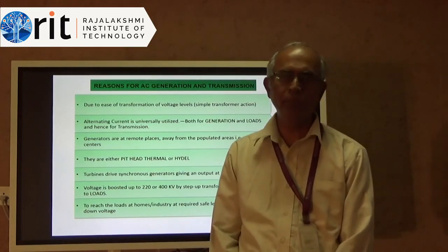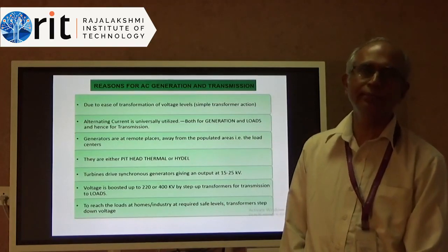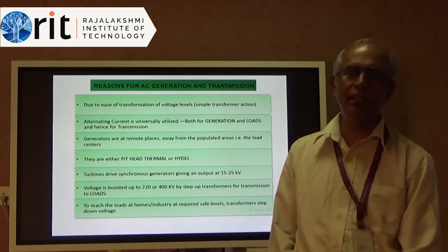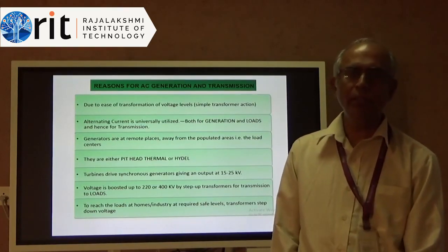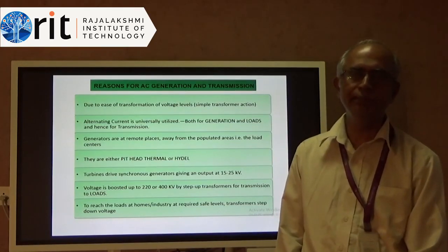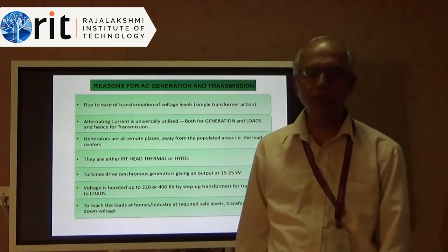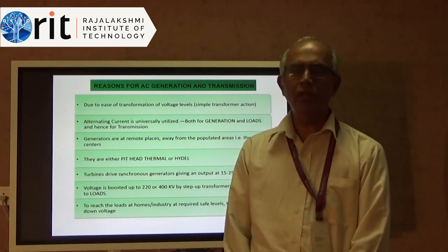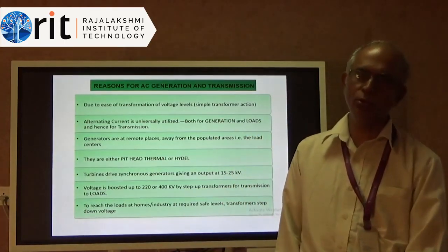And then somebody invented this beautiful equipment called a transformer. There was a possibility that you could scale up the voltage and scale down the voltage from a small value to a very high value. So typically we have transformers which convert voltage from 11 kV to 400 kV, and at the point of consumption, again this voltage is reduced back to the required voltage, maybe 22 kV or 11 kV, or for your consumer distribution it could be 415 volts, or in a single phase 230 volts.